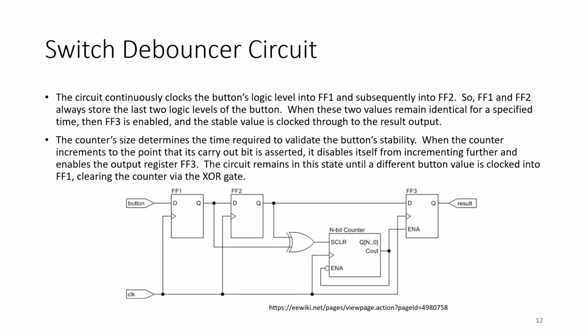Correct. And if the output here is 0, would this flip-flop 3 be enabled? No, it is not enabled, so I will not get the output here. And this output, of course, if I get it, is incorrect because those two are not identical. So I do not need this output. So it is good not to enable it.